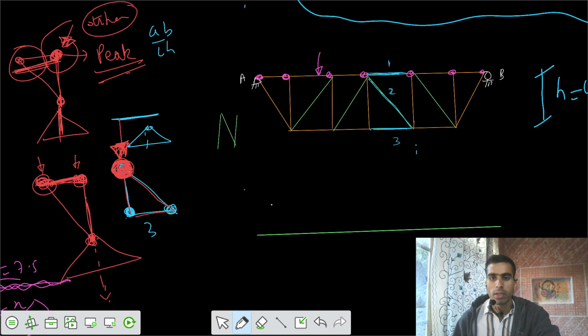So if I take that, I would say the peak gets developed at the mid part. You can get that by the analysis also, if you are good at analysis. But in the strict way, I would say load is applied at this joint for this case only, because load is applied only at this joint. So the peak would definitely be developed at this point only.